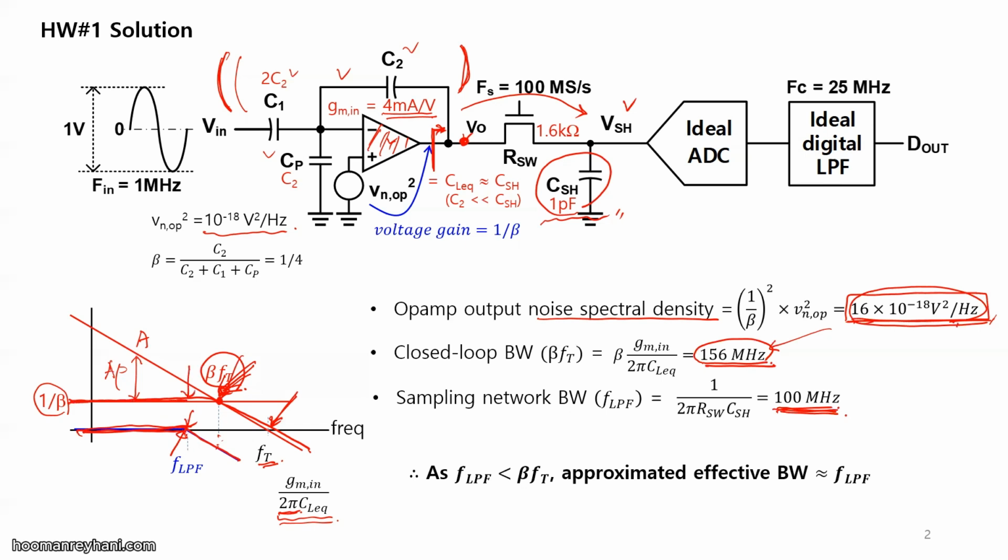We will see the first pole in this entire network, right, up to here. We will see the first pole by this one. So the signal is going to start to drop, right, from this point. And then here at this point, we see the second pole. So its behavior is going to be like this. But for simplicity, I mentioned that let's just assume that this is a single pole system determined by the dominant pole, right?